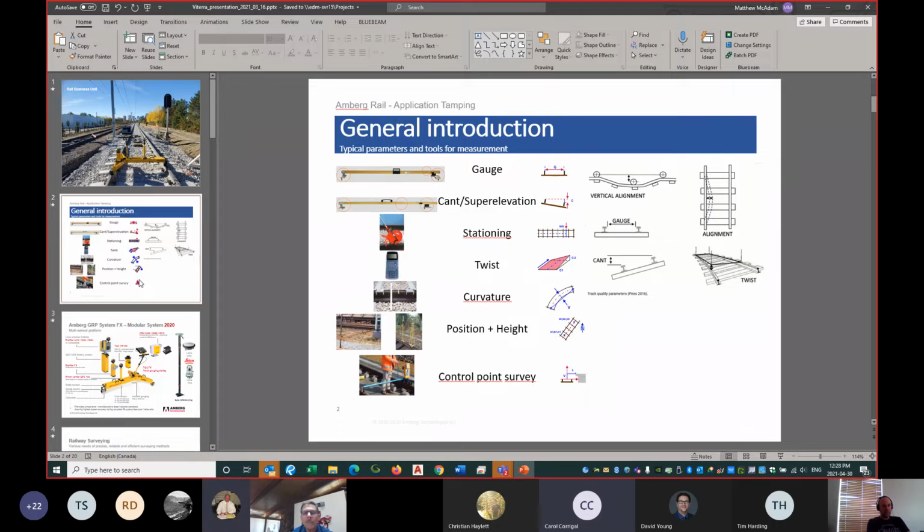So Matt, just further on that, clients have no need to do their rail surveys in the wintertime? When I was talking to the Pembina folk, they had done stuff in November, and it got to the point where they couldn't adjust the track anymore because everything was frozen. Right. So there is that situation where it's too cold and everything's frozen and they can't do anything, and they've got to wait for everything to thaw before they can get back in there and do some adjusting.